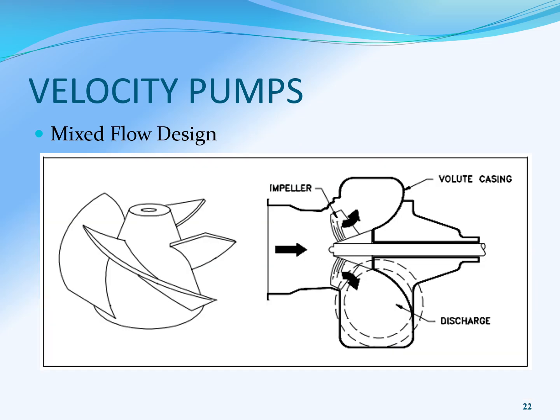Lastly, you've got the mixed flow design. As water is pulled in, it is discharged to either side of this casing, and that's just to move more water. So if you needed to discharge a lot of water, the mixed flow design provides that possibility. You can see water is pulled in, it's sent into the discharge side or the volute casing, and then discharged.